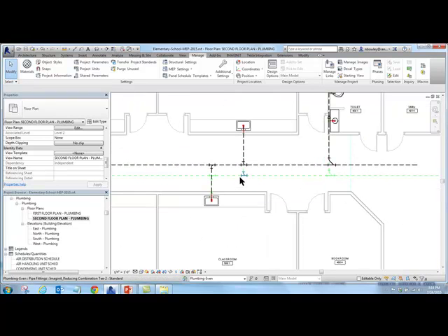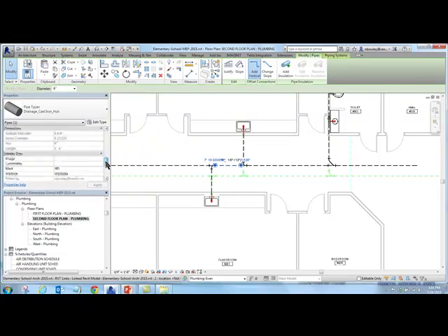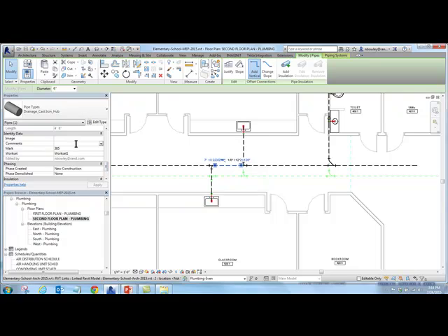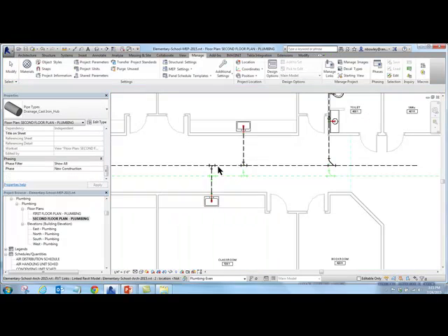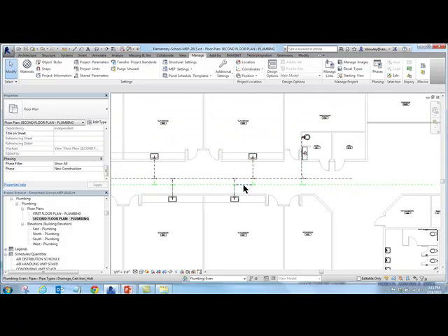Yeah, so he's saying like if you had clicked on a pipe, for example, you maybe could just go into comments for the pipe and just say odd, and you can select all the pipes in the floor and do them all at once. And then you can set up a filter to turn them on or off, and that works too. So, yep, either way. But again, I'm glad I don't have to do it, because that's to show the sanitary in the first floor ceiling, but not the vent domestic water in the first floor ceiling.